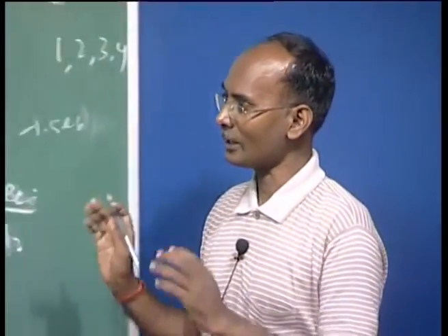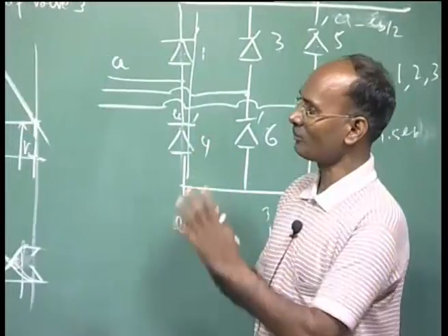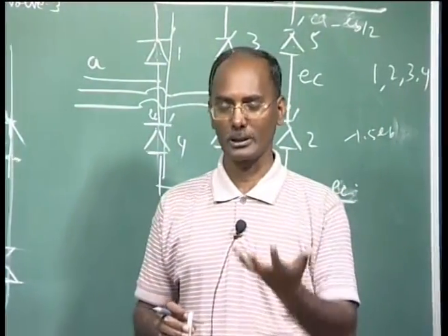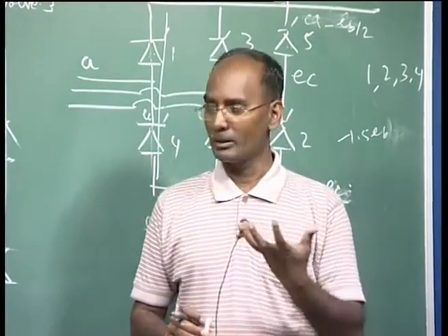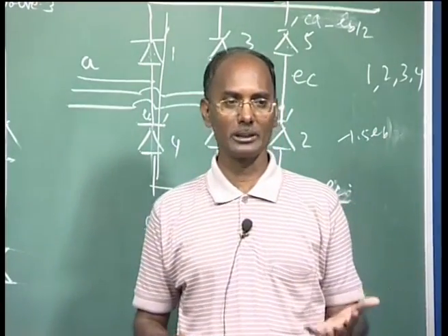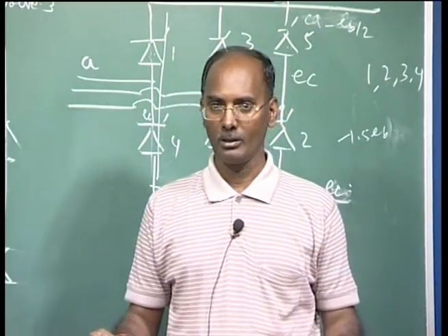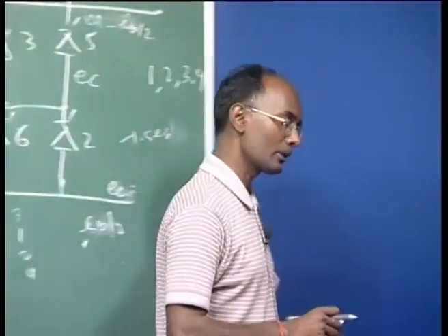So if double commutation failure is occurring, it means there is some problem, maybe in the bridge also, and then it should be blocked and bypassed properly. So this ends commutation failure, and that's why I explained very clearly that commutation failure must be understood properly, because it's a very common phenomenon, and there is no protection scheme for it because it is self-clearing. But if it persists continuously, then we have to take care and bypass or block the bridge.